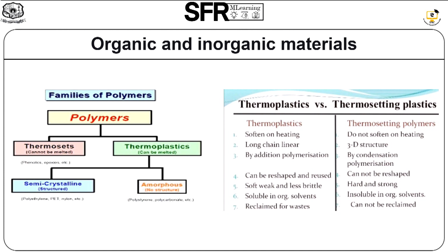The plastics are also used as main ingredients of additives. The lower hardness of plastic materials compared with other materials makes them subject to attack by insects and rodents. Because of the presence of carbon, plastics are combustible, and the maximum service temperature is of the order of 100 degrees Celsius. These materials are used as thermal insulators because of lower thermal conductivity. The plastic materials have a low modulus of rigidity, which can be improved by the addition of fillers, for example glass fibers.